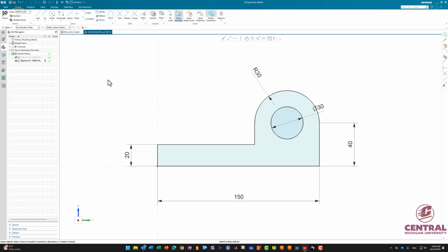Not bad, right? Then you can rearrange the dimensions so that you can easily see what's going on. The only thing left is adding the fillet in a couple of places. So I'm going to have a fillet. Get the size you want according to the book. We need a 4, enter. Then we're going to add the fillet this way and this way.